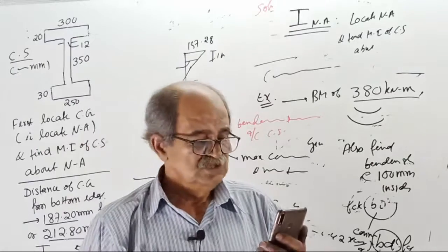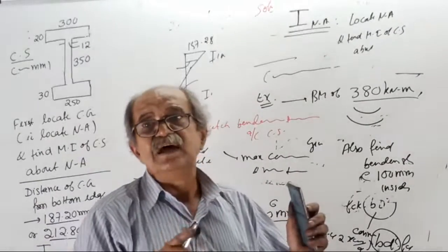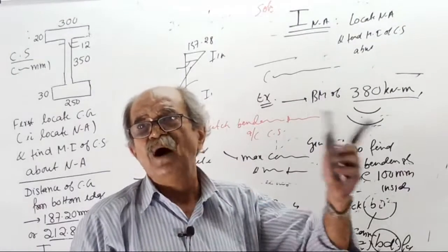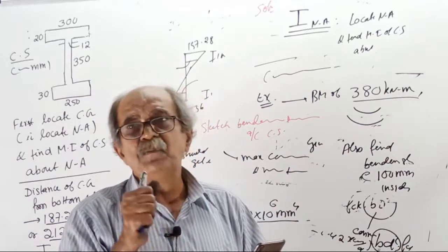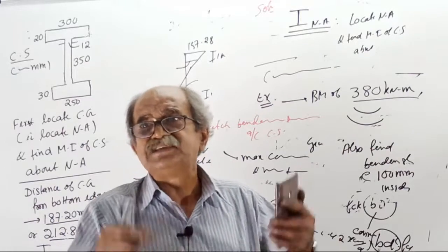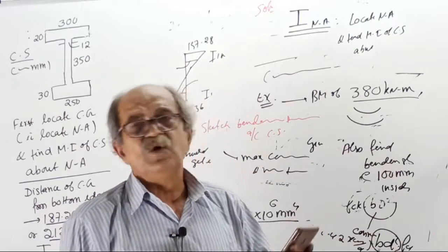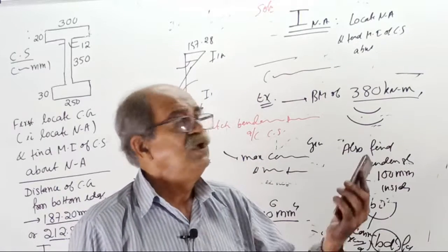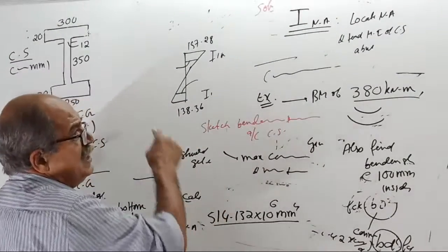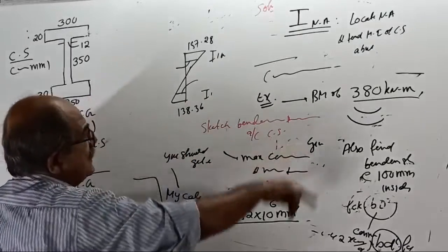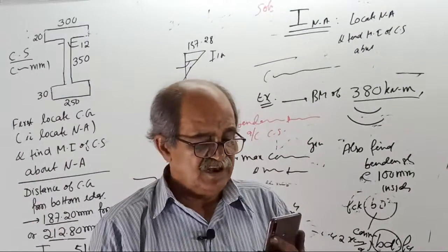Okay, done. So it is better to continue this question and get the stress and simultaneously get MR. I feel your control will be more if you know both solutions simultaneously. This will not take much time. Sigma 1 equals M by Z1, sigma 2 equals M by Z2, or sigma 1 equals M by I into y1, sigma 2 equals M by I into y2. Okay, I will take a photo of this one now, because I am rubbing this one. I will write the section once again.